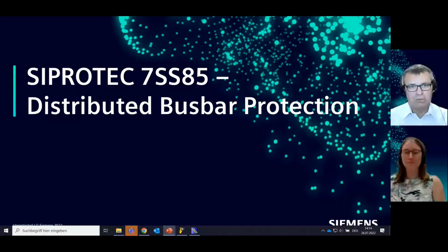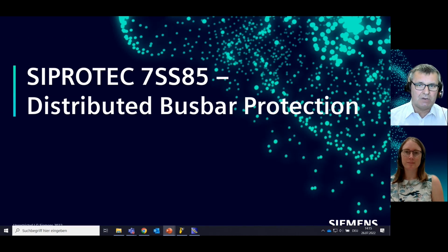In this short video, we will demonstrate how to engineer a distributed busbar protection 7SS85 sensor unit with DIGSI 5. We will do this by the example of a double busbar with 2 feeders and a coupler with 2 CTs. The communication topology will be HSR, and we will use the integrated master clock, a functionality which is available since